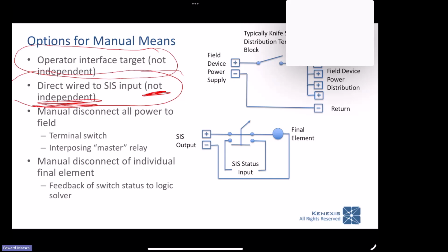So you go from the push button to the IO card, but then the IO card is going to communicate digitally, maybe even up to a mile or more, to the logic solver, which probably is sitting out in the field close to the process. So that's a very common way of implementing push buttons today. They are, or shut down manual means.